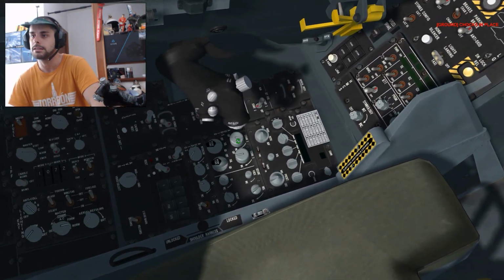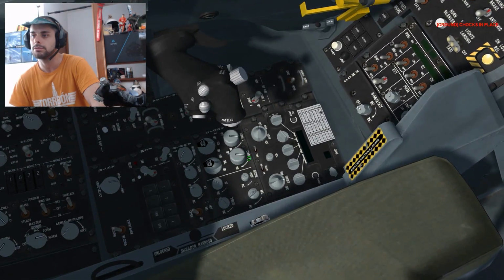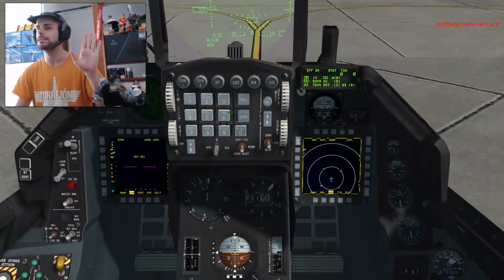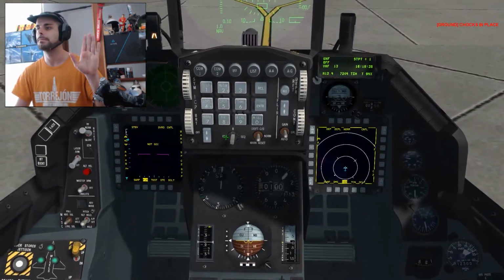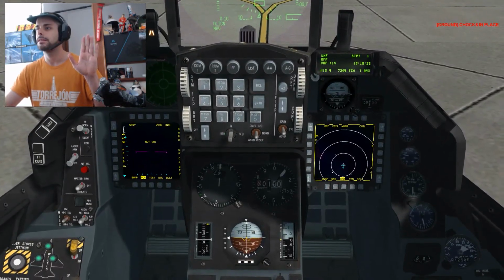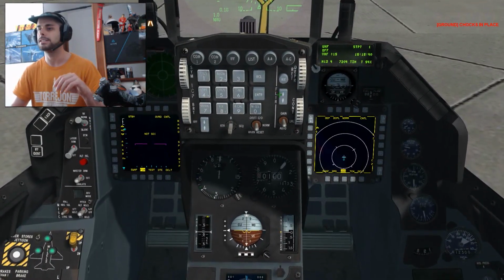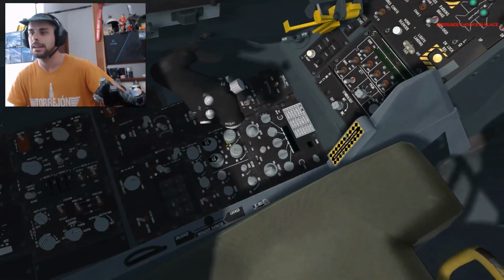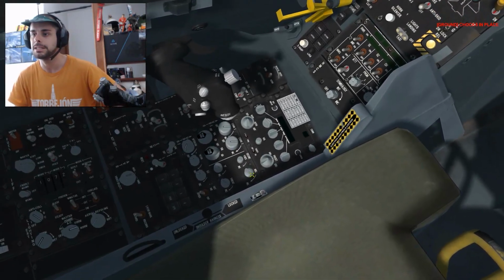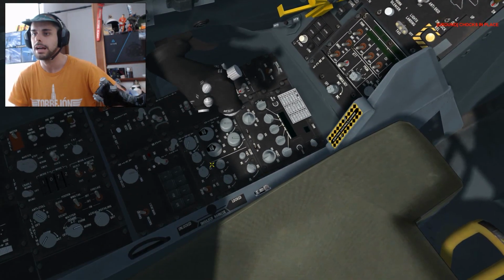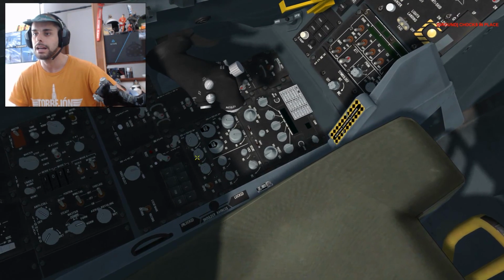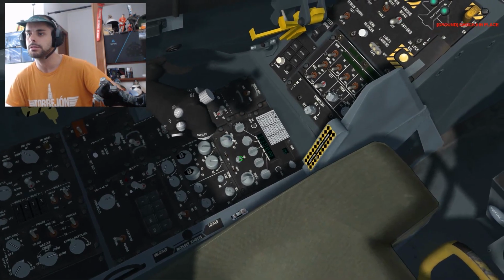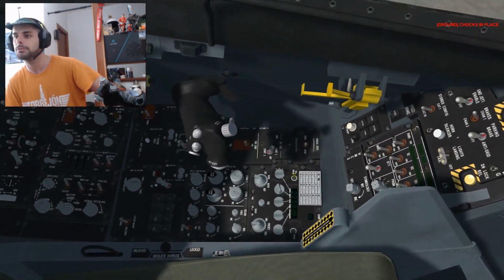Audios, you can start the audio for the radios. Check the missile radio. Information pop-up. Wait a second, please. Runway 09. Expect visual approach. Wind 020 degrees. Temperature 27 degrees Celsius. 1012 millibars. Also ILS, if you need it. TacView is not implemented. And turn on the radio, of course, in both modes. And we are done in almost this panel.